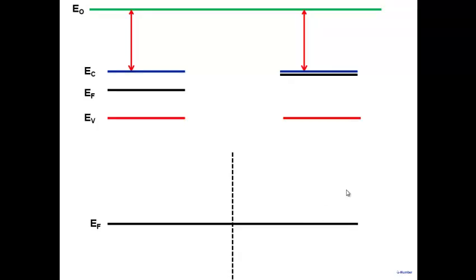Now, the other thing is, as electrons flow from here to here, changes occur, because this part will get depleted of electrons and on this part, some accumulation of electrons will occur. All these things occur close to the interface here. Okay, close to the interface. As you go far away from the interface, your semiconductor is pretty much the same. So what you do is you sketch the energy band diagram far away from the interface.